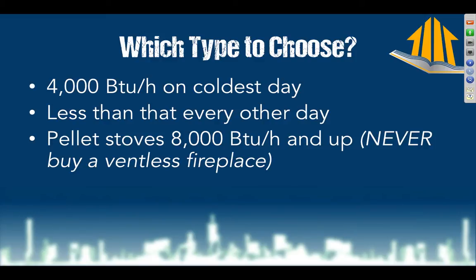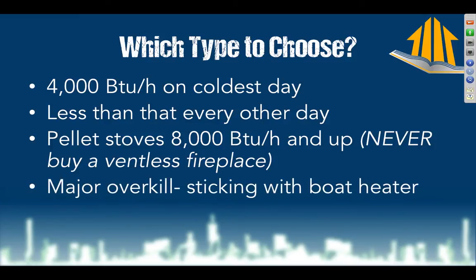But what that means is that as soon as I turn this on, within 15 minutes, it's going to be pretty toasty in there. And remember that a fireplace needs to build up, needs to actually be burning pretty well to be at efficiency. So I'm going to open a window. And now I have completely gotten rid of all the other performance things that I was designing into this, where I'm air sealing and insulating. Once I have a fireplace and an open window, everything is out the window. Literally. It's literally out the window and up the chimney.